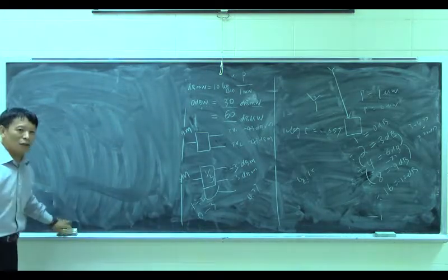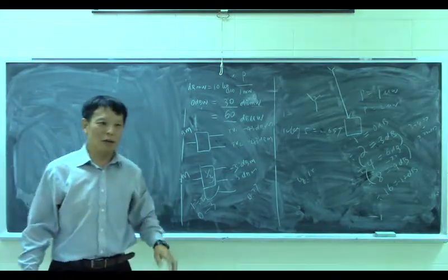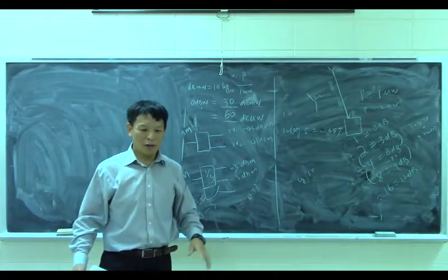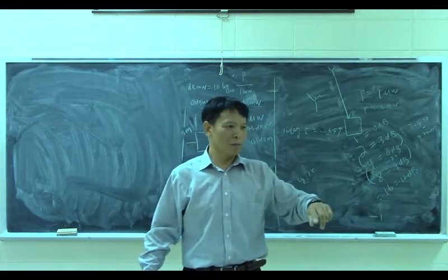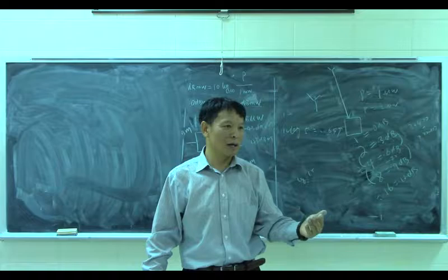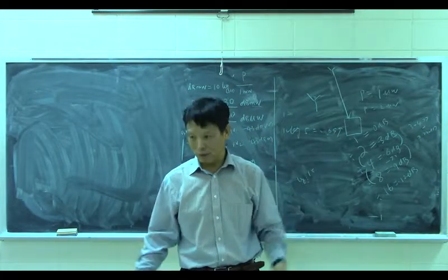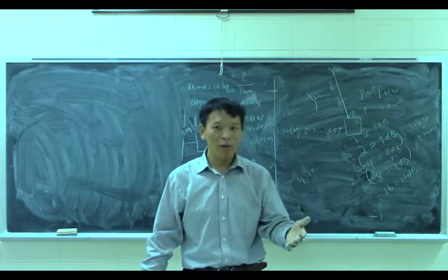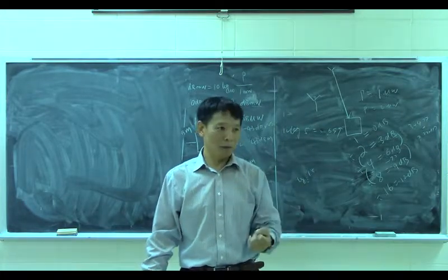In electrical engineering, for example, antenna engineering or microwave engineering, you need a lot of these dB things too. For example, give you an antenna, ask you to measure the characteristics of the antenna. So tell me what is the maximum gain. You never say, okay, equals 100. No way like that. 100 in terms of power would be 20 dB.